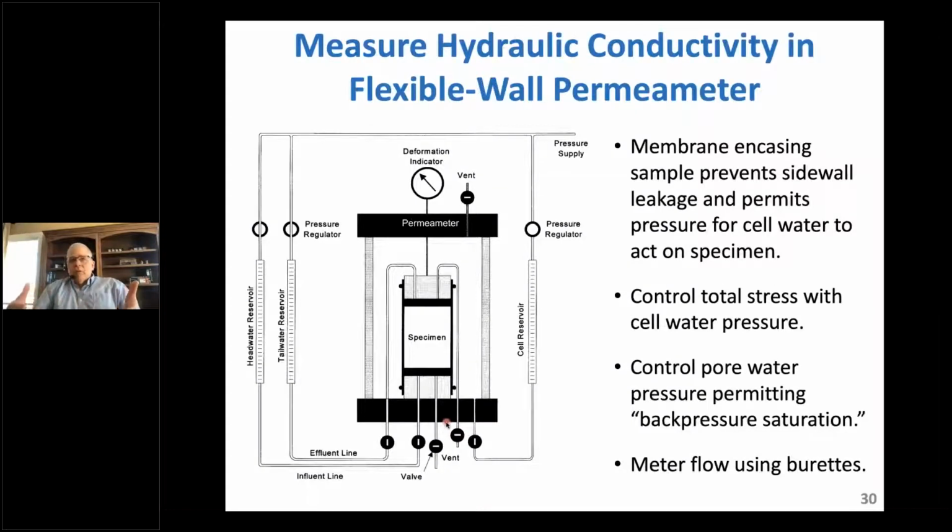Once we understand the chemical characteristics of leachate, we can begin to look at other data and say, based on ionic strength, based on the RMD, should I expect this, and based on the swell index I've measured, should I expect this GCL to have low hydraulic conductivity, high hydraulic conductivity, or I'm not sure, right? And so if it certainly seems to be going to be very high, we probably don't want to go down the road into a great deal of very expensive and long-term testing. On the other hand, if it has a potential to be much lower, well, let's go forward. Let's evaluate whether the hydraulic conductivity is indeed low.